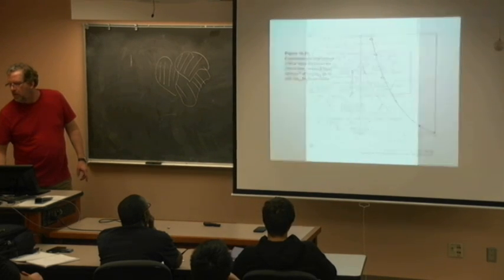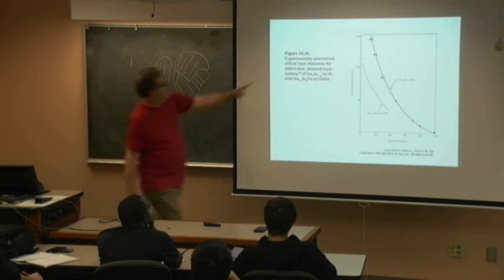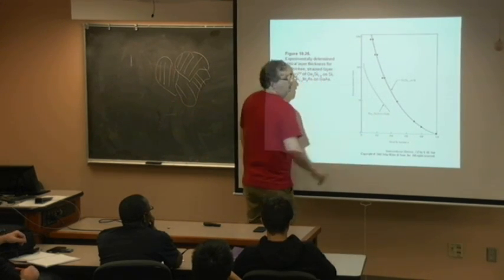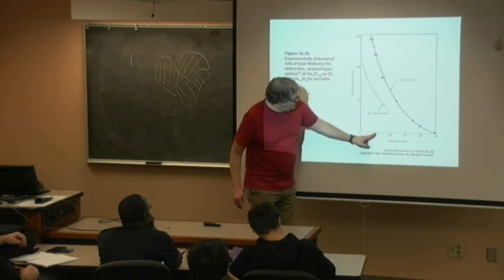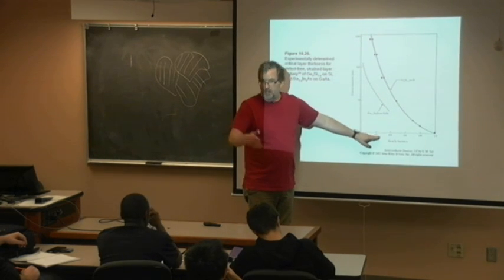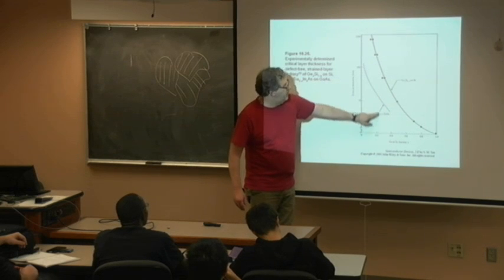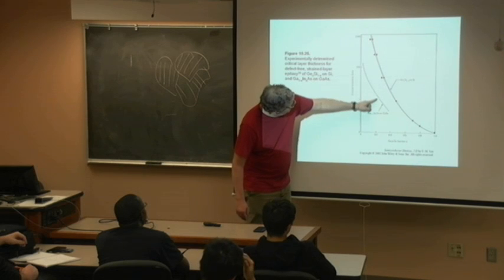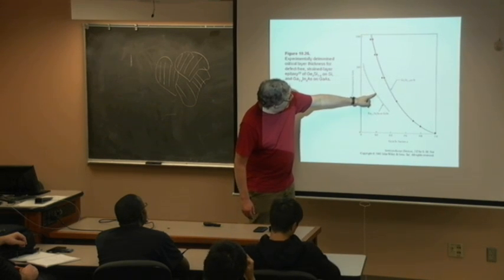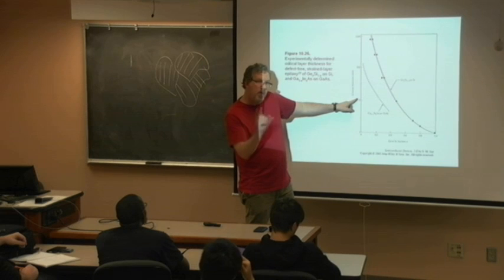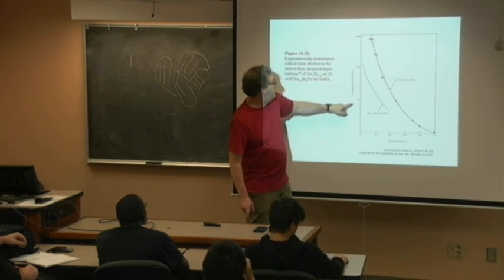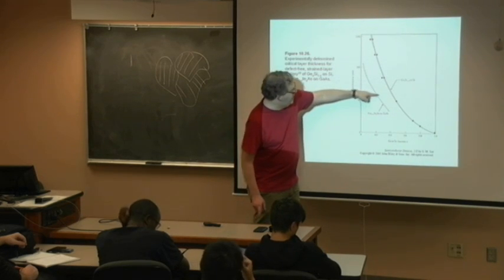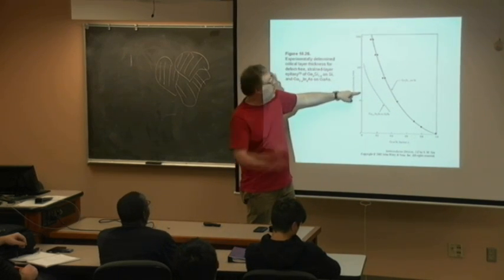So here's the critical thicknesses. Here's that indium gallium arsenide and gallium arsenide. This is one that is used for 980 pump lasers. I'll give you that story later, but my first PhD student formed a laser diode company doing that. Indium gallium arsenide right here. And so there's a limit. He had to make his quantum well laser diodes within probably about 200 angstroms. 20 nanometers was probably a limit of his quantum well laser.